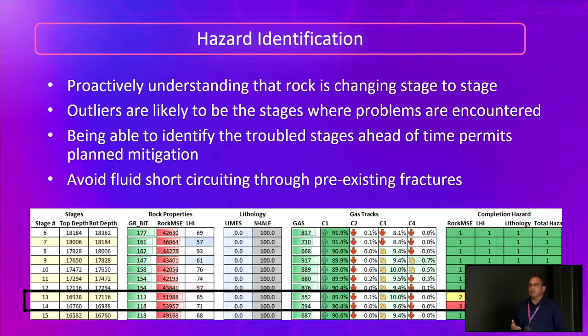So then I can take proactive steps ahead of time, say, if I see a particular pressure signature with the alarms that you can get from Corva. The benefit of that is you can set alarms, and when it comes up and says, hey, we're having trouble treating this stage, then you can easily see what the attribute is that's causing that challenge, and then take a more targeted way of dealing with it. Instead of just instinctively putting more acid in the well or going to a dirty sweep or something, you now have an idea of what is causing that failure or that challenge with treating that stage, and you can take a targeted action to improve it.